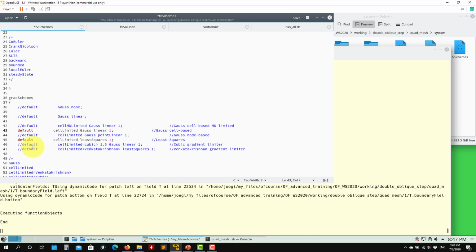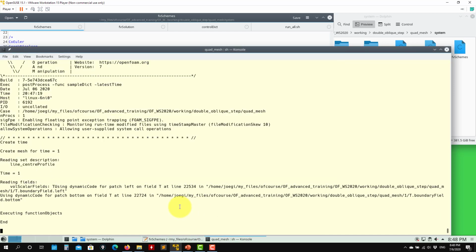Also, you can use it. So again, my preferred way: I start my simulation like this, and then I let it run. You monitor your residuals, everything, and at one point I go to least square. I know that one is more accurate, but I always let it go like this one because I know it's very stable. So you can go here, least square.